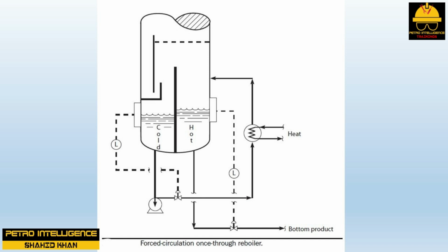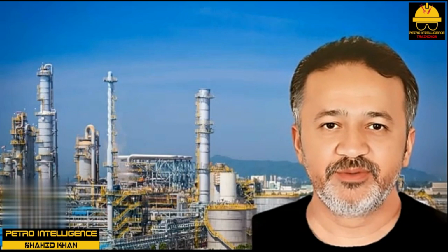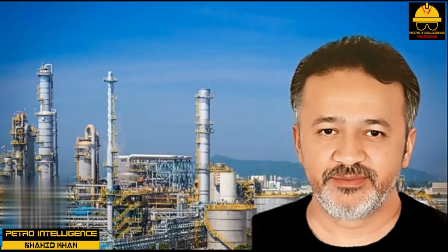control. Further, if the hot side liquid level rises above the reboiler return nozzle, the force of the vapor and liquid rushing back into the column will cause the trays to flood, but the reboiler heat input will not be affected. Most often, forced circulation is used with fired reboilers. If flow is lost to such a reboiler, furnace tube damage is likely to result. Hopefully, this is less likely to occur with a forced circulation reboiler.